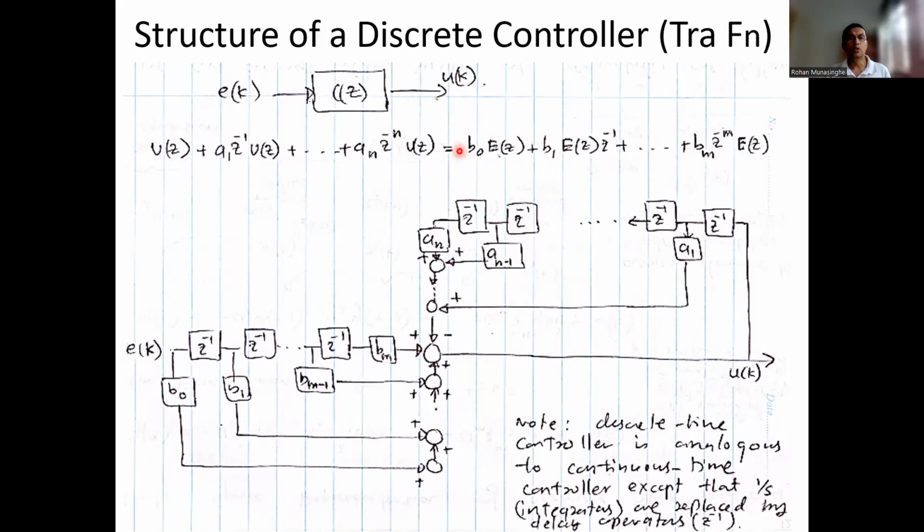Same is true for control signals. Once you decide your control signal, you have to keep it in memory for some time. Because to work out this structure, you need to have u(k), which is the control signal, and u(k) z^-1, which means the previous control signal. And there's another previous term here. All of these terms, as explained by the equation, it may be 5, 6, 3, 4, whatever it is.